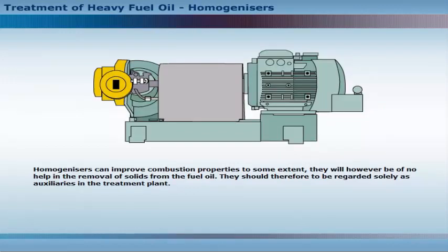Homogenizers can improve combustion properties to some extent. They will, however, be of no help in the removal of solids from the fuel oil. They should therefore be regarded solely as auxiliaries in the treatment plant.